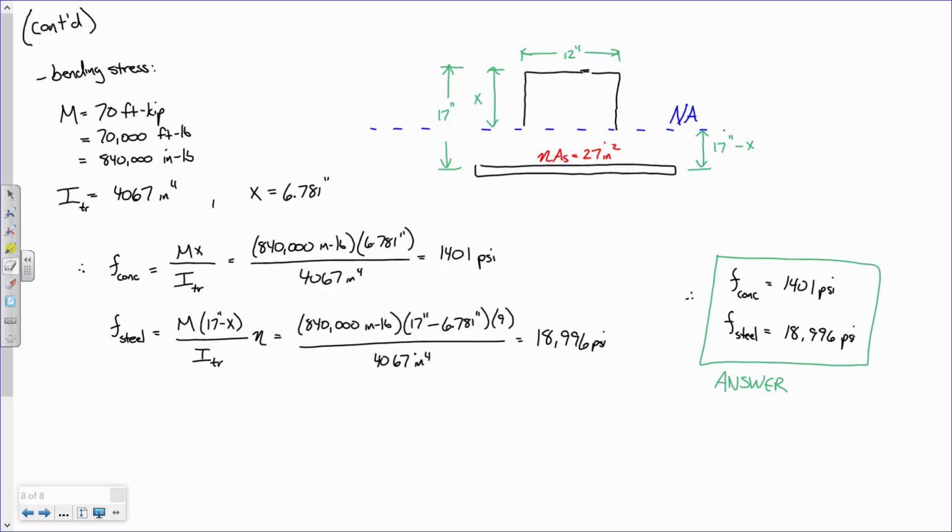So in this situation, the steel is taking on 18,000 psi and the concrete's taking 1401. Yes. So the steel accounts for that much of its strength. No. I mean, you got to understand, you have this big bulky beam of reinforced concrete, and its compressive strength is only 4,000, 3,000 psi. Steel by itself has a yield strength of 60,000 psi. So that's just sort of the nature of the material. But the idea is you don't need that much steel. You see what I mean?